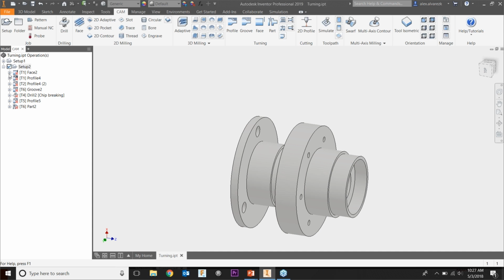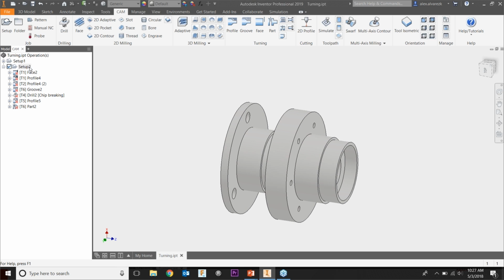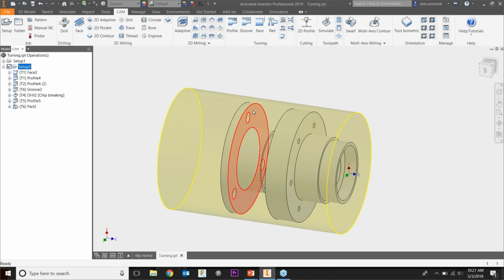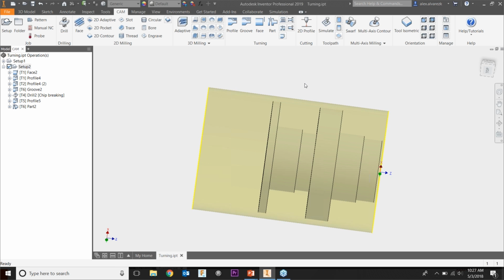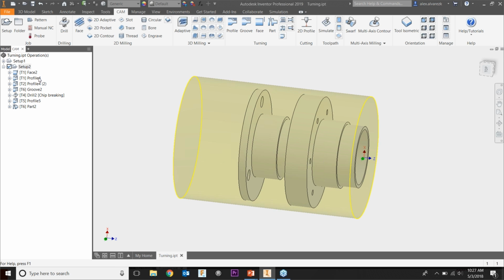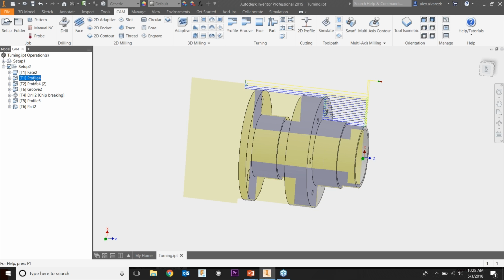And if we look at the toolpaths, right, so now the toolpaths are essentially out of date, right? So we made changes to the model. Hey, go ahead and regenerate those toolpaths. Now, again, some of them may not regenerate fully. So if they don't, just go back in there and reselect some of the geometry that got changed, right? In this case, if we look through them, though, we see that all the changes did go through, right? So again, that saves us.